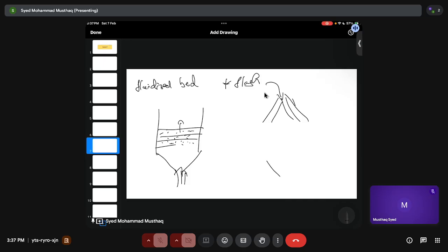Then from the bottom you are blasting air, right? So it is more like a counter current process. The powder is coming down, but the air is going up. So it happens in seconds. That's why we call it a flash. And there is flash melting, flash reduction, flash oxidation. There are different types that we do, which will come into picture in the next sessions. So it happens within seconds. That's why we call it a flash.